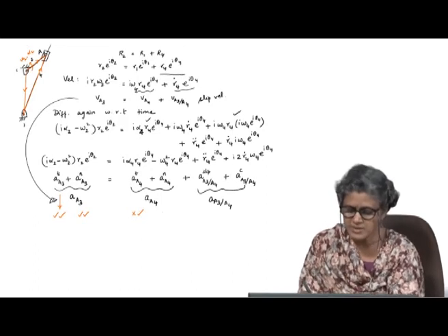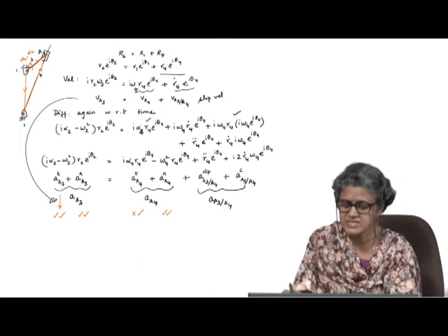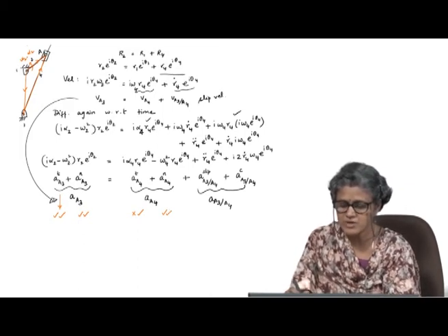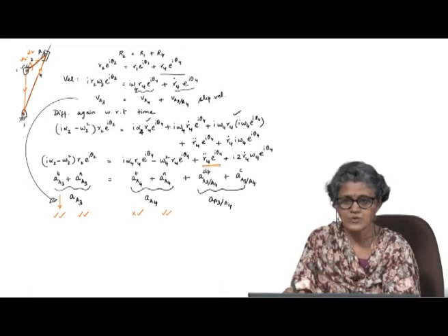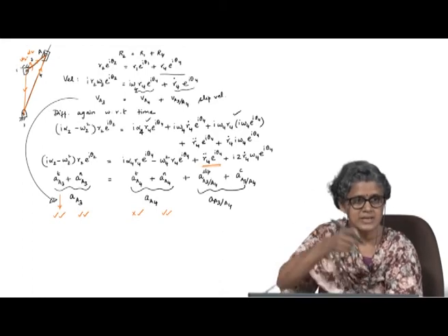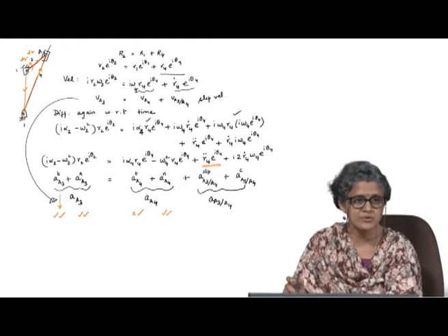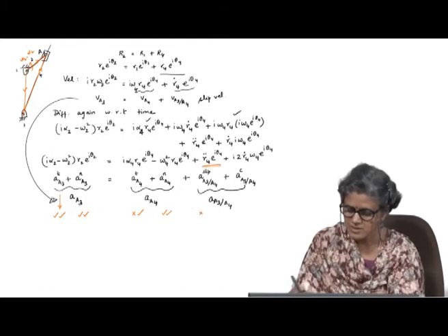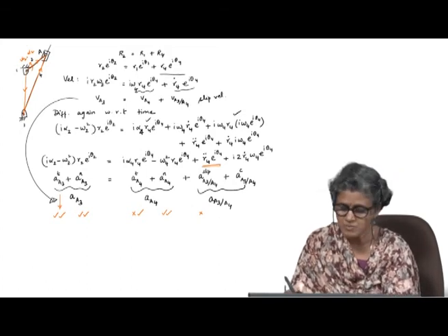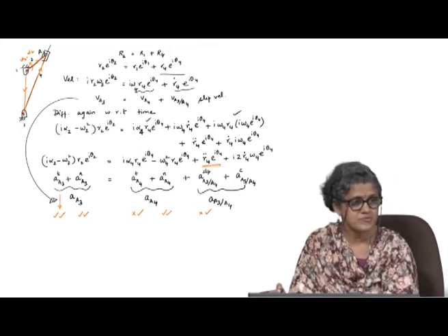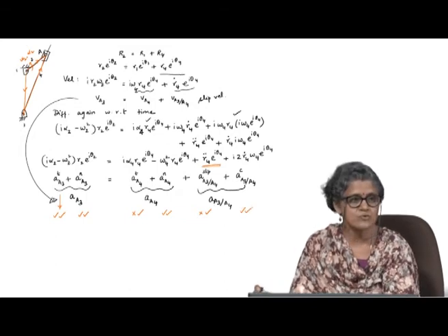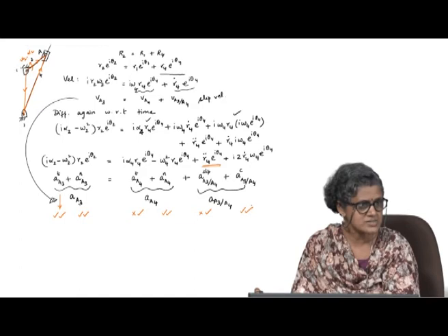Normal component completely known. In this case the slip component, what do I know about it? If I look at this term here, I know the direction, it is along the link, but I do not know the magnitude of R4 double dot. So, here R4 double dot is unknown, but I know the direction for this term, and for the Coriolis term again it is completely known because of the velocity analysis.